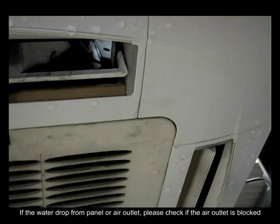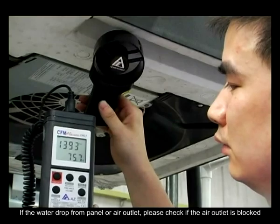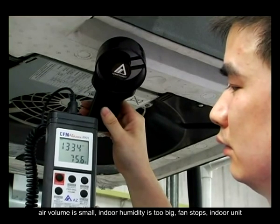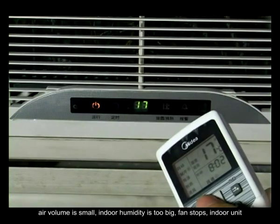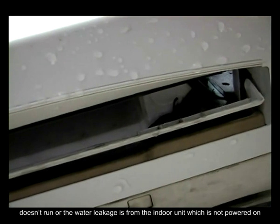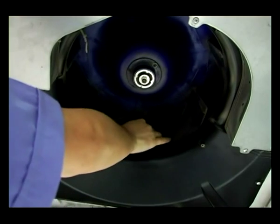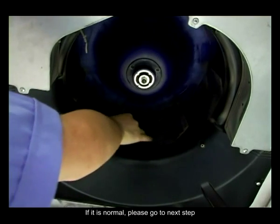Step 2. If water drops from the panel or air outlet, please check if the air outlet is blocked. Air volume is small, indoor humidity is too high, the fan stops, the indoor unit doesn't run, or the water leakage is from an indoor unit which is not powered on. If a problem exists, please repair it one by one. If it is normal, please go to the next step.